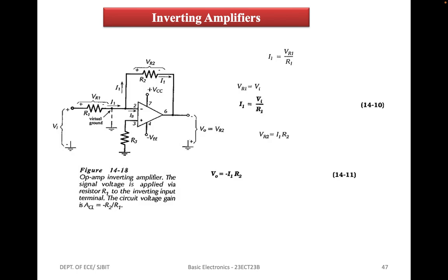If the input of the inverting amplifier is grounded, the circuit is seen to be exactly the same as a non-inverting amplifier with R3 as the input resistor and zero input voltage. Thus, negative feedback occurs to maintain the op-amp inverting input terminal at the same voltage level as the non-inverting input terminal. The output impedance of an inverting amplifier is calculated in exactly the same way as for a non-inverting amplifier. As in the case of the non-inverting amplifier, the output impedance is very low for an inverting amplifier.